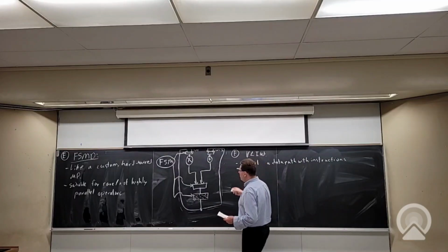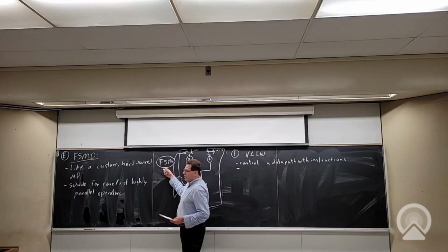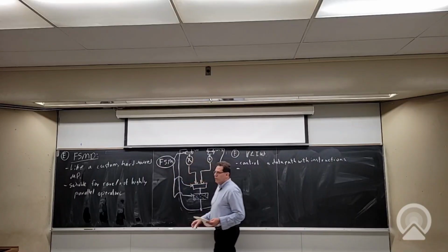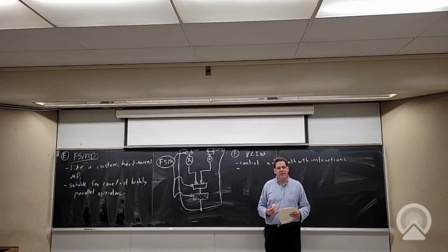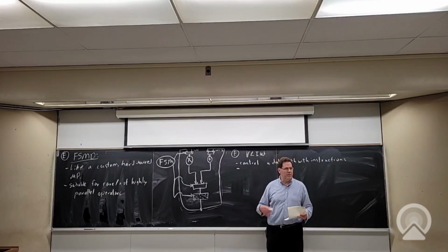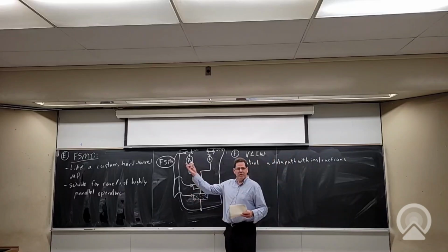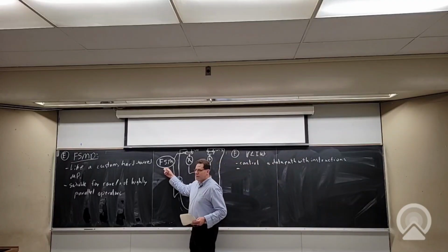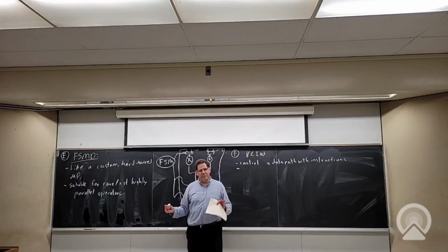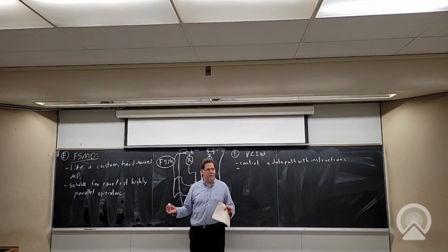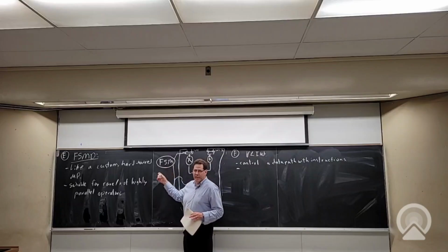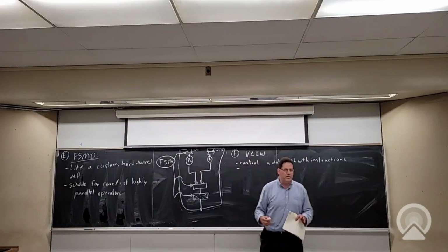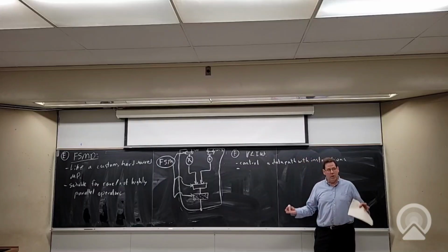Okay, and there's a certain point, if you're doing pretty simple control, this finite state machine is normally smaller than if you built an instruction memory and you built the decoding logic to decode what it means, and some branching logic to decide what the next instruction should be. But as this finite state machine starts getting more and more complicated, there's a certain point at which first it's hard to write, right? It becomes a difficult design problem. And secondly, it actually eventually gets less efficient. The finite state machines, as they start getting big enough, they start getting slow and they take lots of logic.